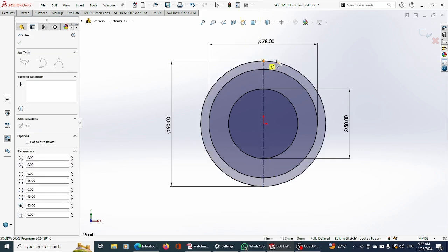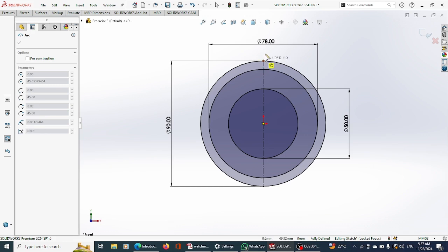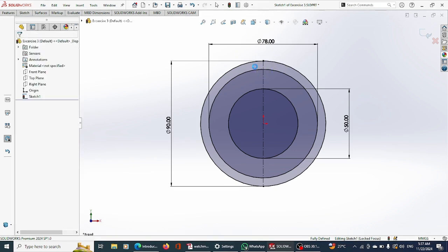And then I'm taking it back to here. Sorry. Just once you see something like this, SolidWorks behaves like this. When you click on a point with a straight line, and then you come back to that same point, it will change to an arc. So escape, hit enter again.